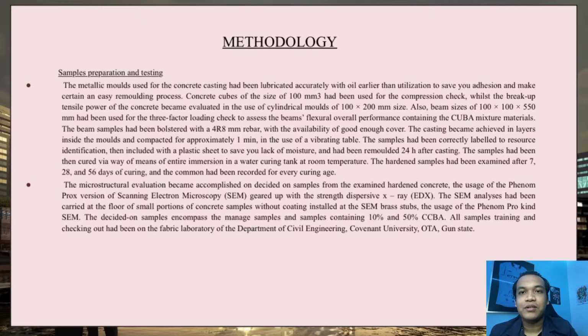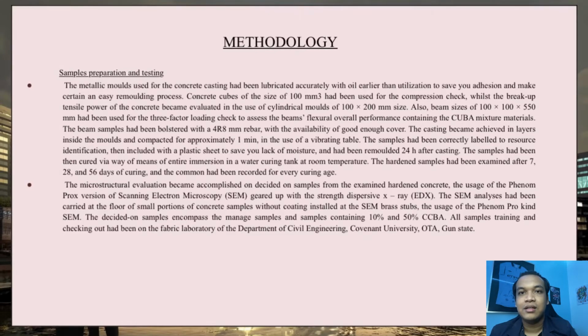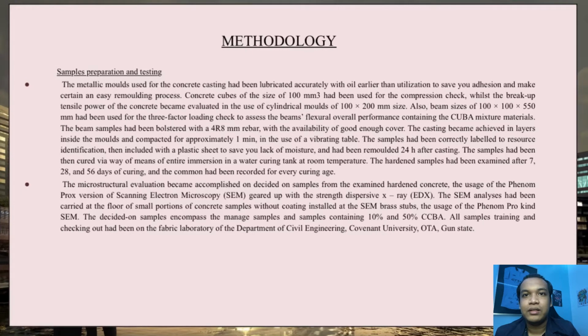Concrete cubes of 100mm size were used for the compression test, while the splitting tensile strength of the concrete was evaluated using cylindrical molds of 100 x 200mm size. The beam samples were reinforced with 4R8mm rebar with adequate cover.